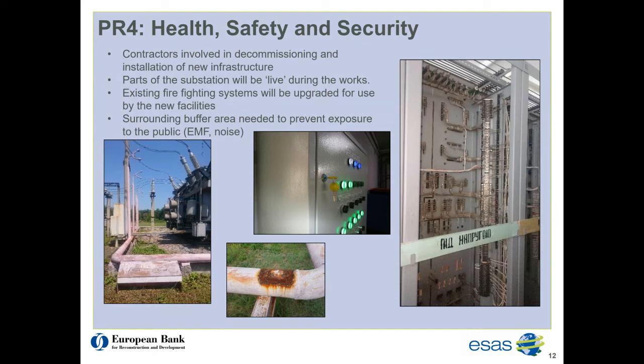Asphyxiation associated with the release of sulfur hexafluoride. Dusting to live infrastructure, which could lead to unreliable operation and failure. The reliability of the existing firefighting system, it appears poorly maintained and corroded, as you can see in the bottom picture. The assessment needs to consider the suitability of extending this firefighting system to the new infrastructure.